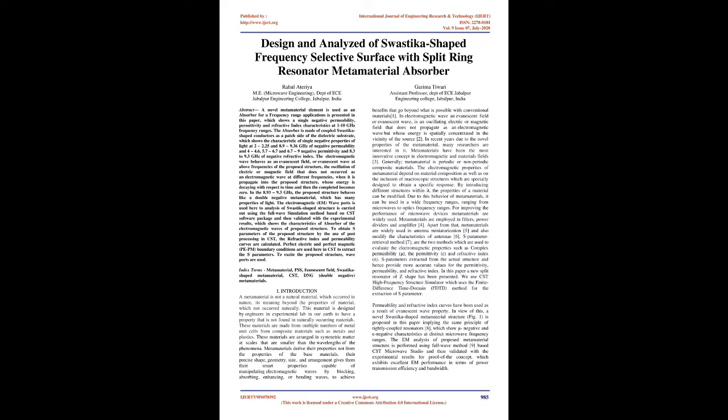Electromagnetic wave ports are used here for analysis. The Swastika-shaped structure is analyzed using the full wave simulation method based on the CST software package and then validated with the experimental results, which show the characteristics of absorption of electromagnetic waves by the proposed structure.